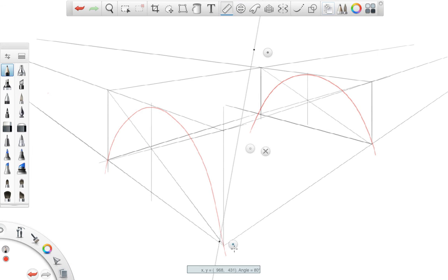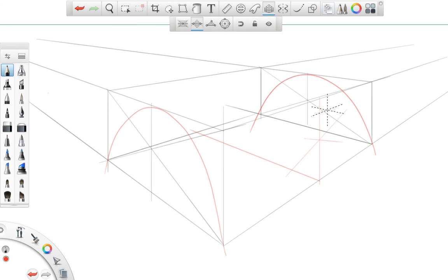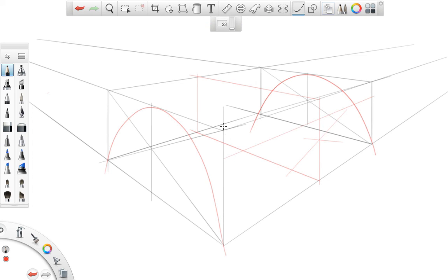There is an alternative way we can use, and instead of putting the top view onto the bottom face, we actually work with a side view. This has one advantage I would like to show you, or is very useful for certain applications. So here you see I put down my left and right midpoints, and now here I put down a line because I would like my curve to start going straight down, then arc in, and then go up and stop being straight.